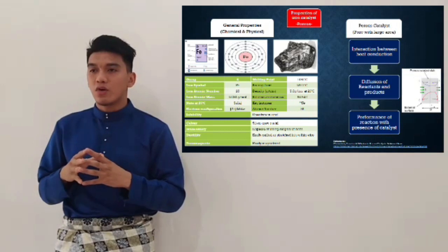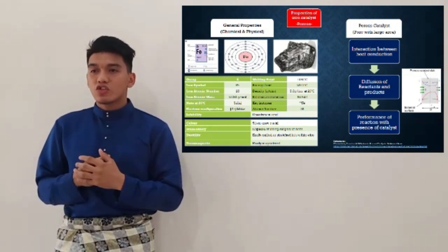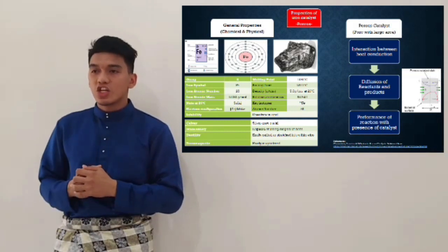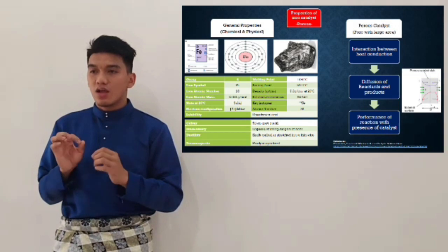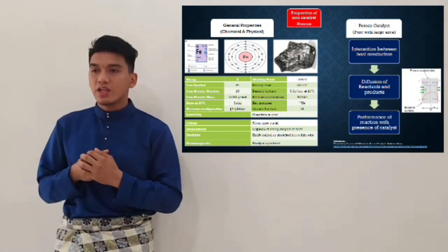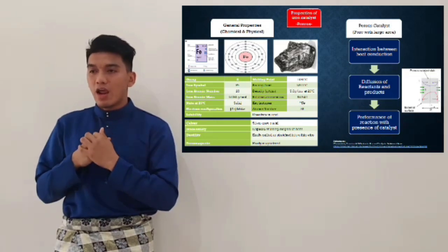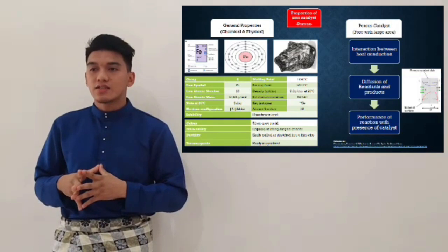In a large pore catalyst with a pore diameter above 50 nm, the transport of heat and chemicals by convection, in addition to diffusion, inside the catalyst needs to be considered. Such big pore solids are used, for example, in hydrogenation reactions, in reactors, in the production of ammonia in the Haber process. Okay, that's for the porous catalyst.